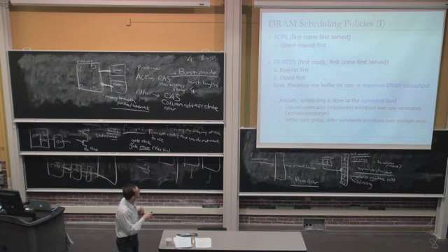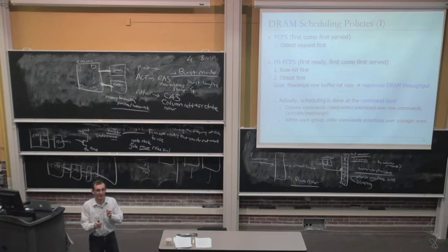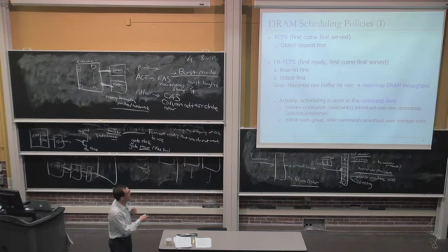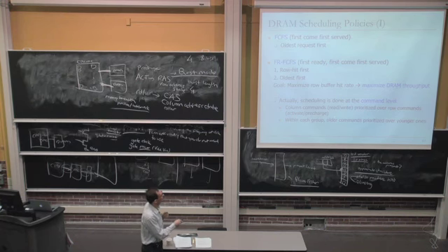Just one point, scheduling is actually done at the command level. So you don't actually send a request, and this is clear, hopefully. You have column commands, and you have row commands. For each request, the controller keeps track of: does this need an activate at this point? Does this need a pre-charge? Does this need a read? Does it need a write? And then among those, it schedules.